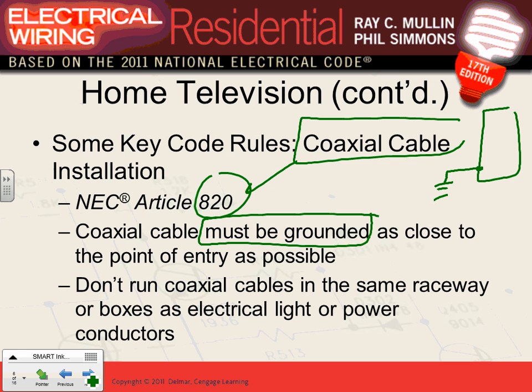Everybody knows the coaxial cable has the signal in and the shield out, so you ground the shield as close to the point of entry as possible. That's required by the code. You bring the coaxial cable, take the shield, and ground it with number 14 copper, insulated or bare, and then you're done. You ground it where? You take it to the grounded intersystem bonding jumper, they call it, or a ground rod. That's it. If you read through this article, ground it as it enters.